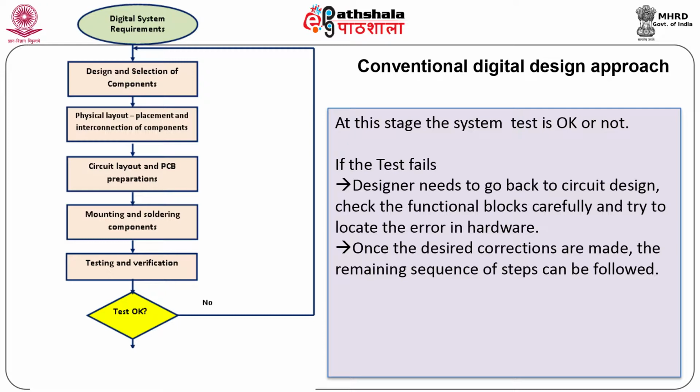During the testing and verification process, it may happen that there is some problem, such as a functional mismatch, timing mismatch or logic problem. If the expected and implemented functions are different, then it generates a functional mismatch. The designer needs to go back to the circuit design, check the functional blocks carefully and try to locate the error in hardware.